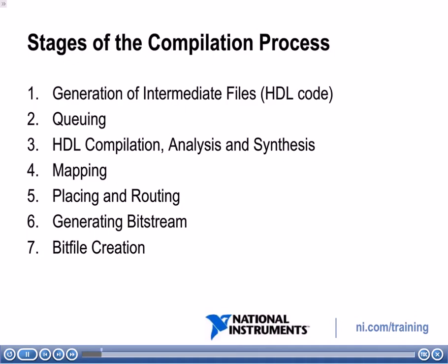After that, we'll get to generating the bit stream, and this is where the compile worker creates binary data that LabVIEW saves inside a bit file. And then lastly, we've got the bit file creation. This is where LabVIEW saves the bit file in a subdirectory of the project directory, and from there you can either download or run that application on the FPGA.